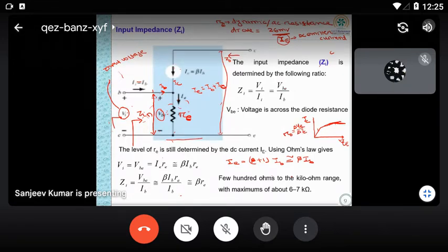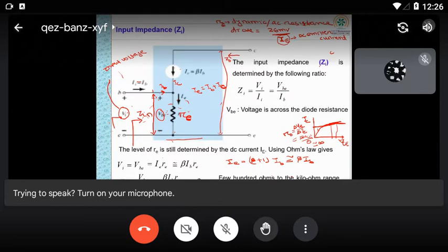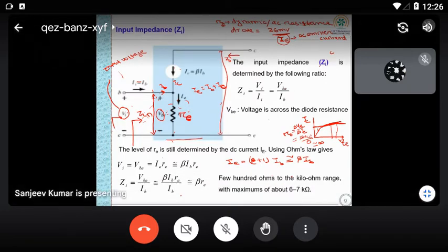So a change in VC will be there, for example I'm taking this voltage, and the change in current I'm taking here will be 0. So now it is change in VC divided by 0. What will be the value? It is approximately infinite. So the output resistance of your transistor will be infinite, and the output impedance, which is equal to your R0, is then also infinite.